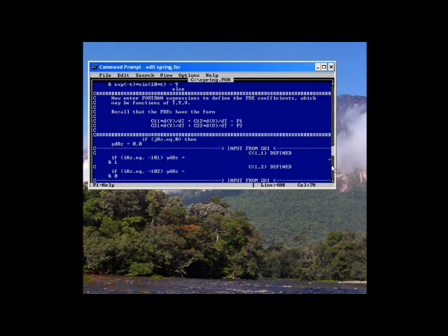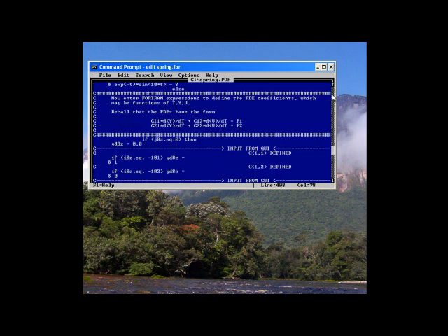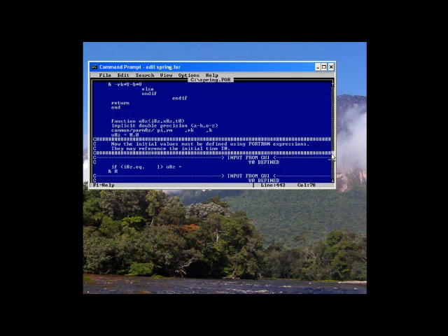Okay, so here's the actual partial differential equations, and they're defined above, since C11 was 1, C12 is 0, F1 was V, because that's y prime equals V. Second one, C21 is 0, C22 is M, or Rm, times V prime is equal to, that was the minus Ky minus BV, and so forth. So typically you'll make some errors here, and then you can correct them in the Fortran. You don't have to go through the whole GUI session again.